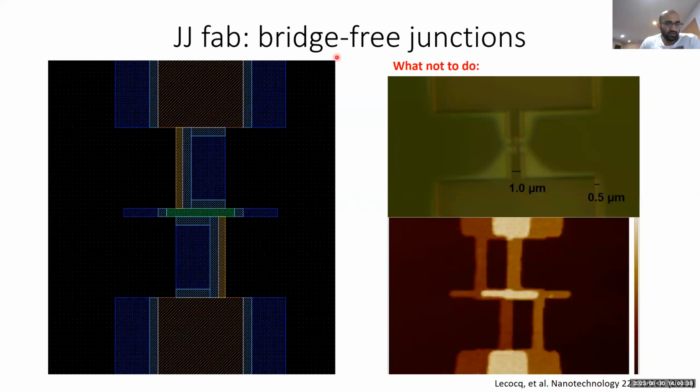So this is sort of the general CAD file. Here in the brown, I have fully exposed regions corresponding to the wiring that leads up to my junctions. And in the yellow, I have the very skinny leads that I've fully exposed. And in this rectangle, I have the artificial undercut that I'm inducing using a low dose. Okay, and importantly, there are two separate doses here.